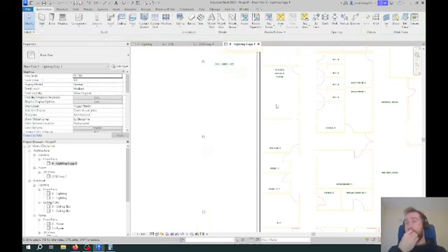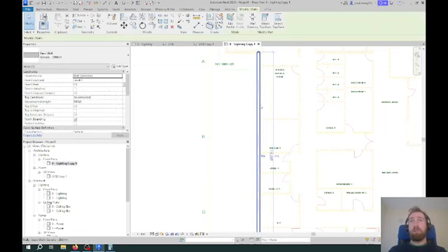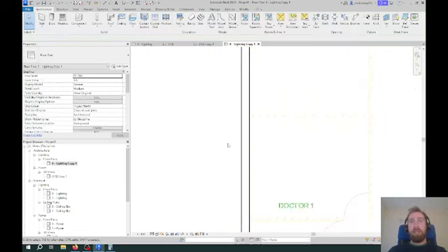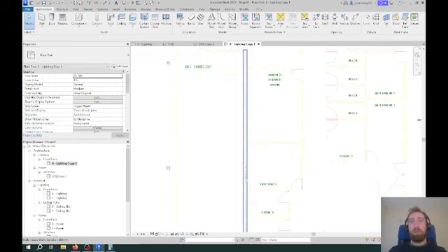The other thing that's very helpful for when you're constructing these drawings is if we select the wall option here, you'll see we can see through it when we have it selected, but not when we don't have it selected. But we can help with that by changing the visual style down here to wireframe. And now we can see the construction element we put in, but also we can see what's underneath it for when we want to place windows and doors.